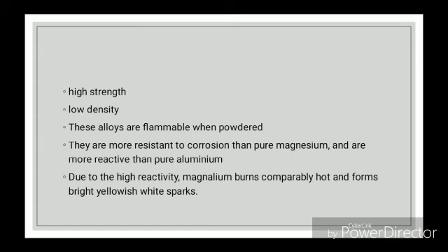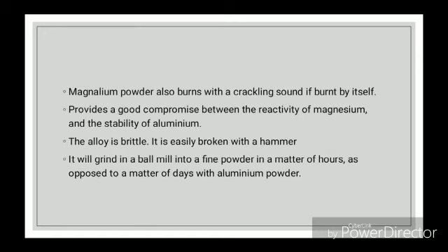Other properties include high strength and low density. These alloys are flammable when powdered. They are more resistant to corrosion than pure magnesium and are more reactive than pure aluminum. Due to high reactivity, magnesium burns comparably hot and forms bright yellowish white sparks. Magnesium powder also burns with a cracking sound, if burned by itself, and provides a good compromise between reactivity of magnesium